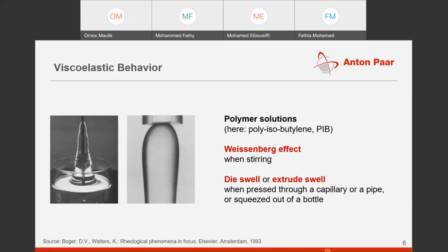Now, what exactly is viscoelastic behavior? I suppose you have seen these examples, or probably in your practical life, or you have studied them. In case you don't know these effects, you can see on the left hand side of your picture, this particular effect is a rod climbing effect. What happens is when you stir a viscoelastic material, the material itself will attach itself to the stirrer and climb up.